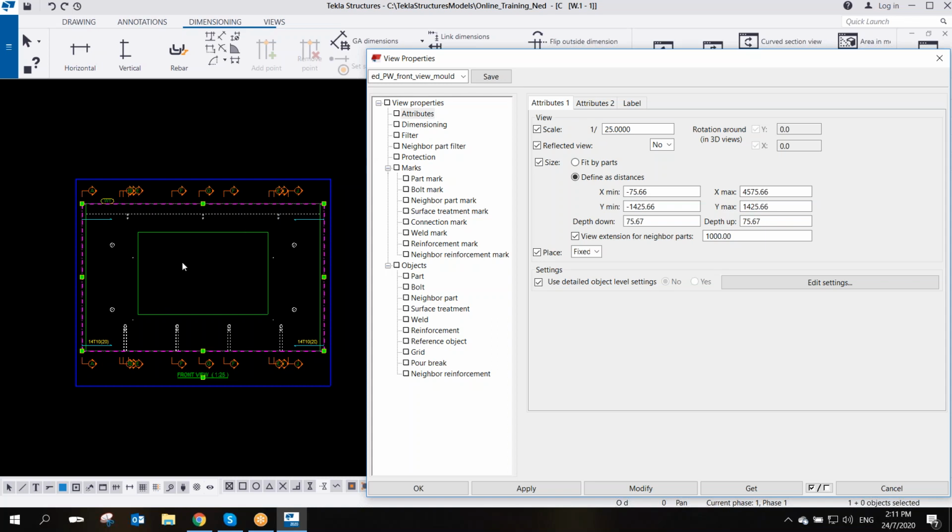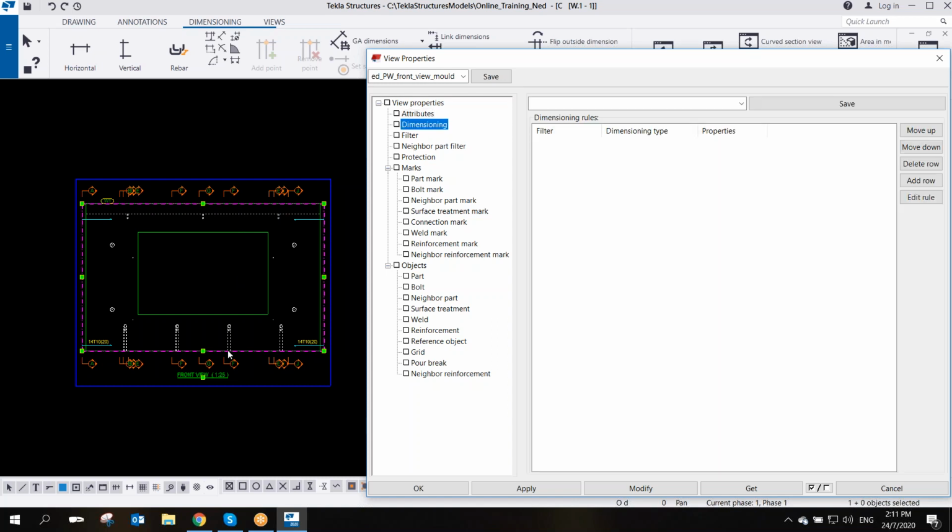So we do this one once, especially for the wall. We do it once for the wall. Then all the rules that we have created can be used for all the walls, for all the same category. But of course, for the column, you may have different rules. You may have a different combination. So you need to create certain rules for each type of your precast.